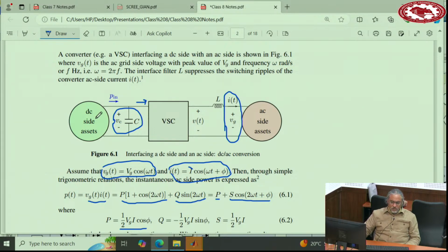Obviously, the obvious solution is that if you increase the capacitor, those ripples go down and down. So in this scenario that we just discussed, if you choose a 20 millifarad capacitor, the ripples really become 2 volts or 2.6 volts. So probably for that power rating of 10 kilowatt, a plus or minus 2 volt ripple, PV doesn't care about that.